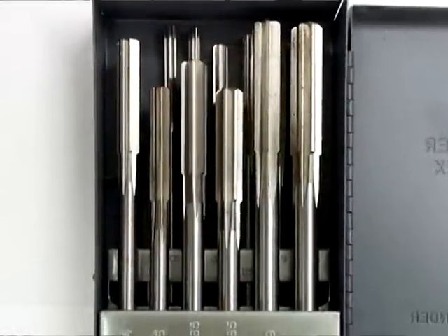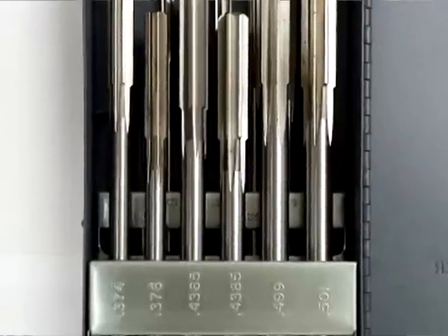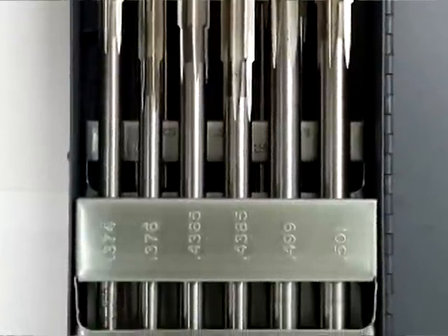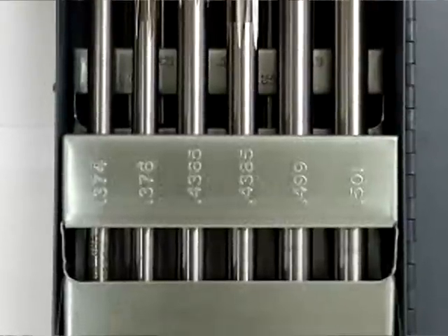And it looks like a normal set of reamers until you scan down a little bit and see that it's an under and over size reamer set. And what does that mean? That means, and this is a fractional set, that for each dimension of reamer you have a thou over or a thou under. So if you have 0.5 dimension, you don't have a 0.5 reamer in this set, you have a 501 thousandths of an inch or a 499 thousandths of an inch reamer.